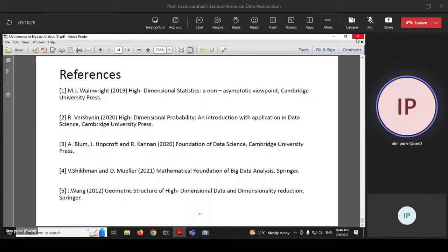The forecast covariance in Kalman filtering plays the role of background covariance. So the model, I can compute the forecast covariance through the model. Then you also have the responsibility of knowing the observational covariance. And you need to combine the two.